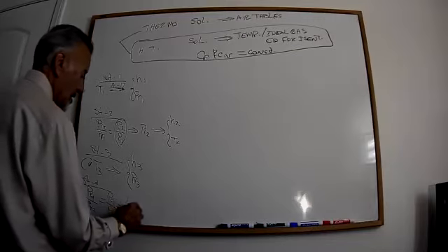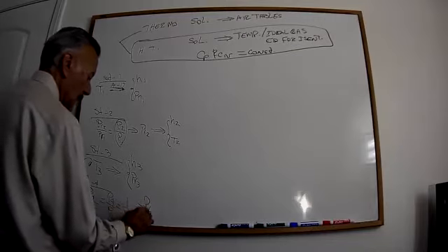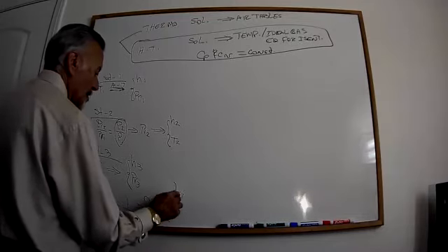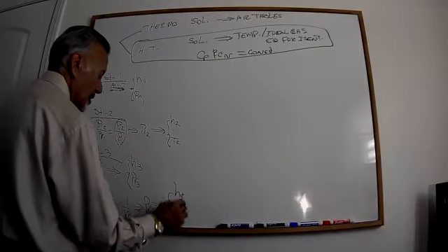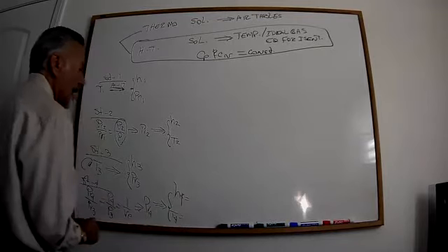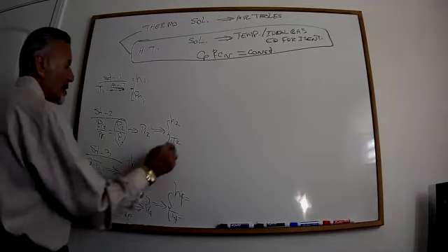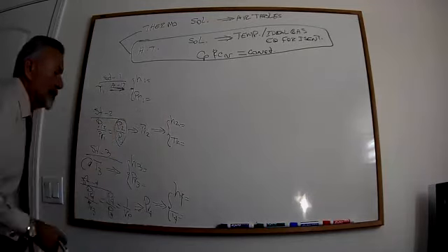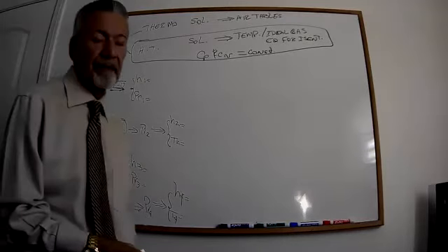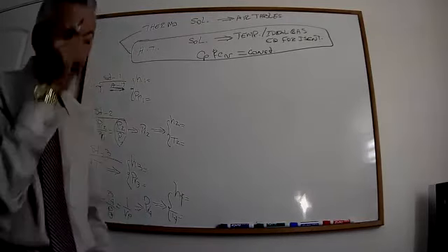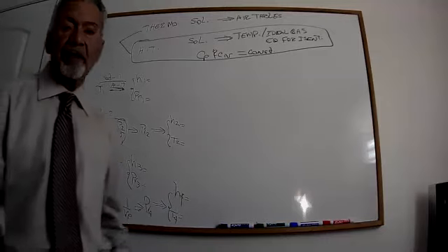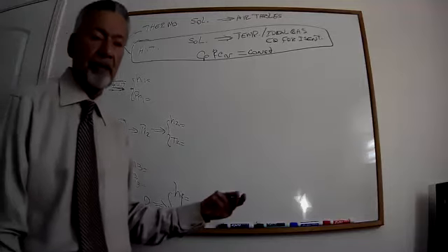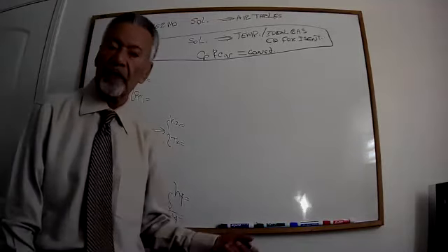From there, you will find PR4, and then you go to the table again, you find H4 and T4 if you need it. That's how we're going to do the examples. Once you have all the H values, then you know how to find Q in, Q out, W in, or work of a compressor and work of a turbine.